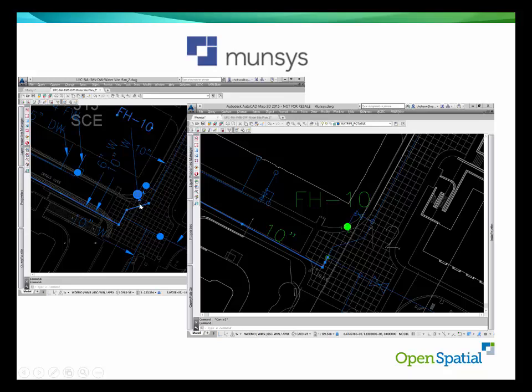See this line here is a CAD polyline, and it's not broken where this line intersects. So this pipe, there would be some sort of fitting there. You see this hydrant? Obviously someone exploded the block, and now it's actually a polyline with 2 other little line segments for the pumper connections. The text is just text. This hydrant has no idea that it's a fire hydrant 10 in this instance.